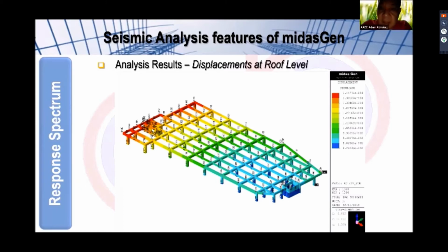But that is, of course, based on the design basis earthquake. Well, it's very obvious that considering the actual ground shaking, it seems that that maximum displacement was not reached. Because if you go back to the previous results of the time history analysis for the ground motion data, the maximum displacement is about 3 millimeters compared to about 145, which is the maximum.